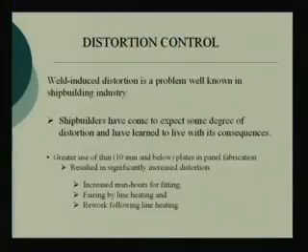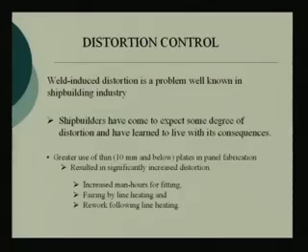So, for all the accommodation structure, all the deck house, they are generally of plates of 4-5 millimeter thick, even 3 millimeter, but high tensile steel 3 millimeter plates. So, it is very prone to buckling, primarily buckling. When the gauge is thinner, buckling is the problem. So, that has resulted in significantly increased distortion because of these thin plates.